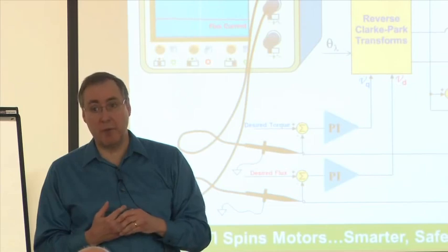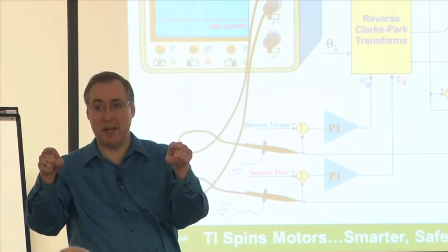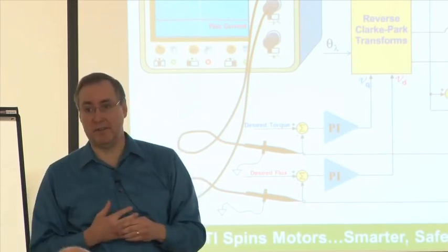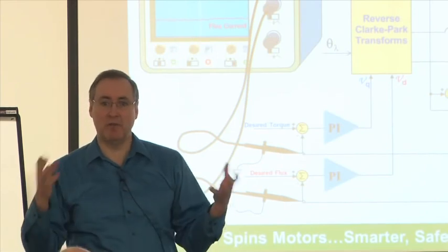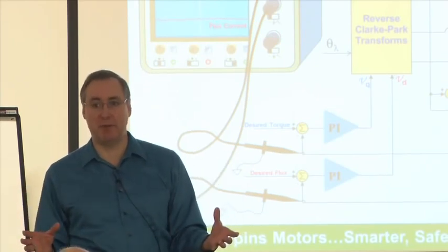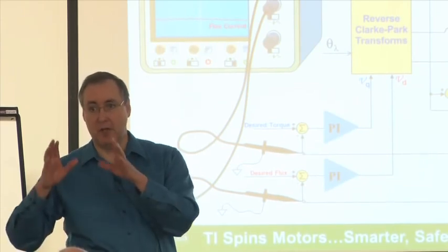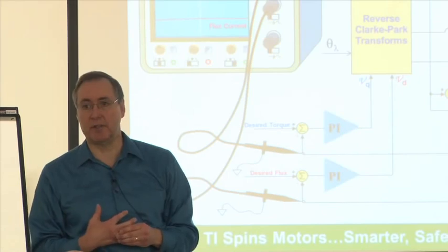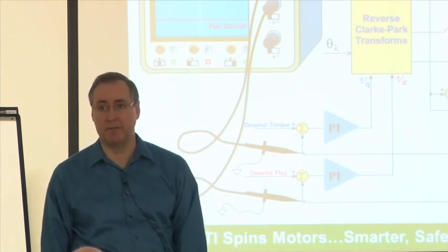If those current waveforms are really whipping, and you take sample A current and then you take sample B current, they're different in time, so you're going to get a motion artifact on phase C calculation. And then I'll extrapolate on your question to ask the other question, and that is, what if you're sampling voltage waveforms and current waveforms? Well, again, ideally all of them would be captured at the same time, but at least that part is a little bit more forgiving. If you don't sample the voltages at exactly the same time that you sample the currents, it's a little bit easier to deal with, but you want to get those current samples as close to the same time as you possibly can to prevent motion artifacts.